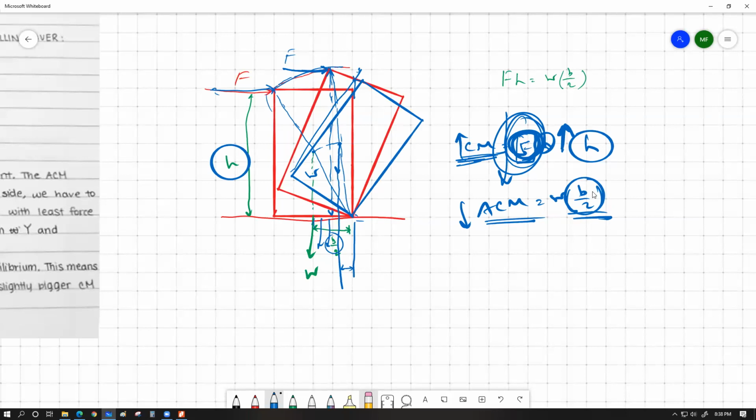I mean, when the COG becomes perfectly above the pivot point, up to this point we have to apply the force, and I am discussing what the variation of this F force would be throughout the motion from the starting all the way to the tipping point. Initially, the required force would be the biggest. As the rotation continues, the F force required to maintain the rotation would slowly become smaller and smaller. Make sense? I think so, sir.